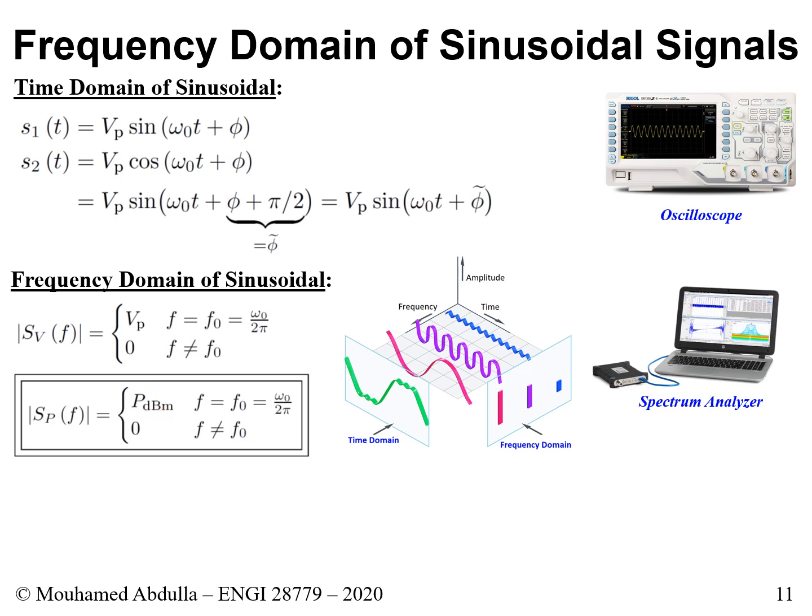Let's do it together. So the following is what we do. We begin by saying that the power in dBm for the sinusoidal is equal to the power in dB watt plus 30. This comes from the equation that I just showed you earlier. Next, we know that the power of the signal in dB watt is basically equal to 10 log 10 of the average power, and then your 30, you just carry it next to it.